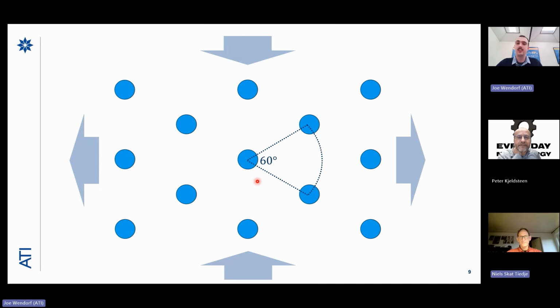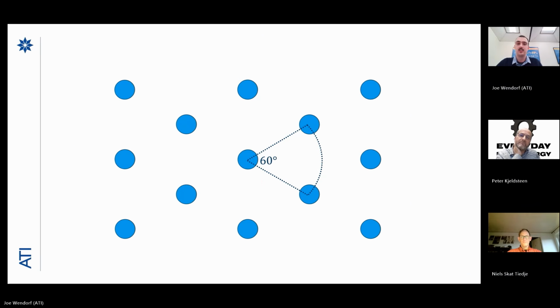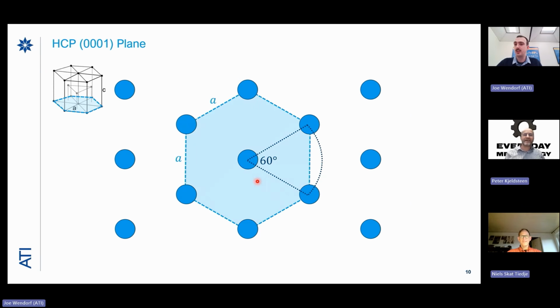And now, if you look at this deformed BCC crystal, this is an HCP crystal structure. Cool. There are some more details that I'm glossing over here about how this second plane of atoms deforms. But basically, if you apply a strain to the BCC crystal structure, you can deform it into an HCP crystal, which is the alpha phase.